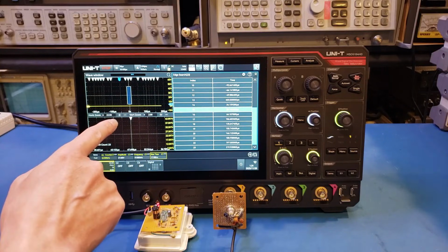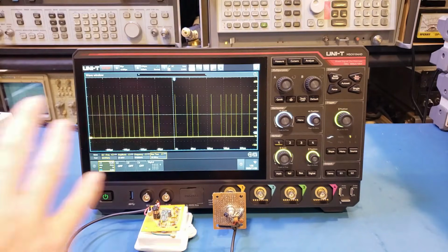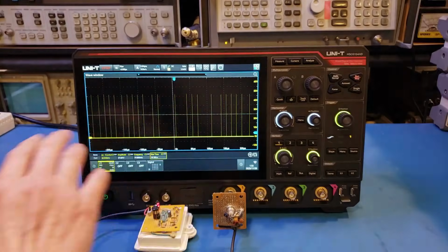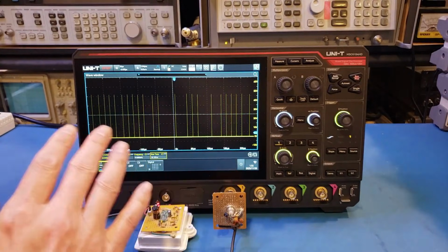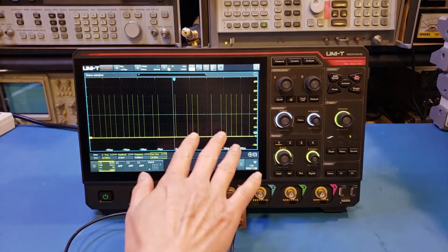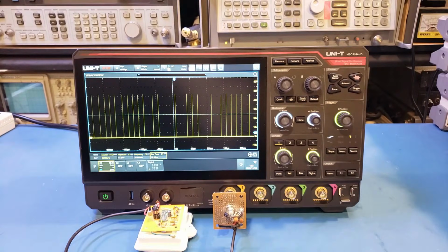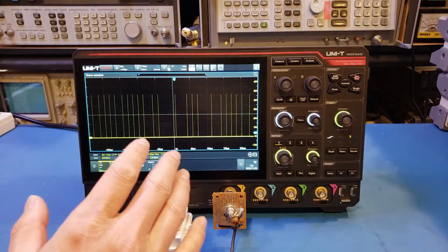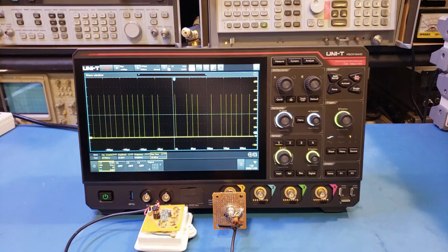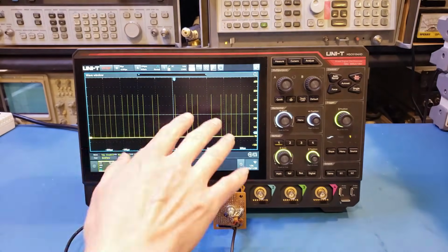Now you can see that we actually navigated to that pulse. So it's great that we have a huge amount of sample memory and we can capture a lot of waveforms, but from the capture we just did, you can see that the waveform is actually pretty sparsely populated. Although we capture a lot of events, the majority of the waveform memory is actually wasted because there's nothing interesting between these avalanche pulses. And this is because in standard triggering mode, once the oscilloscope is triggered, it will continue sampling until the sample memory is filled. And in this case, when the signal is sparse, you will end up wasting a lot of sample memory.